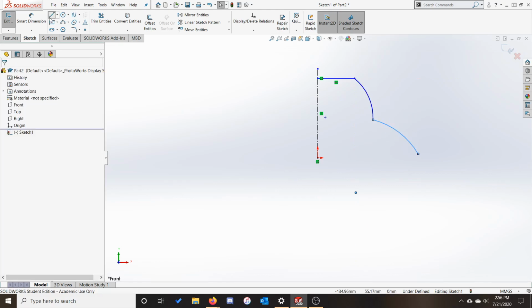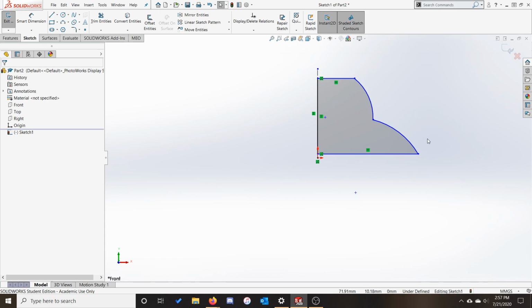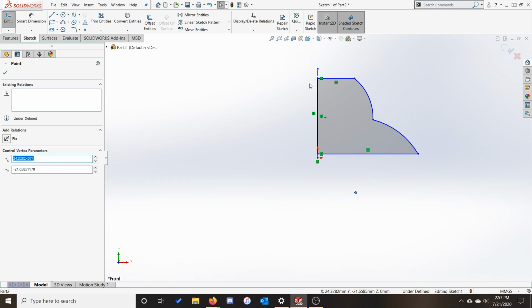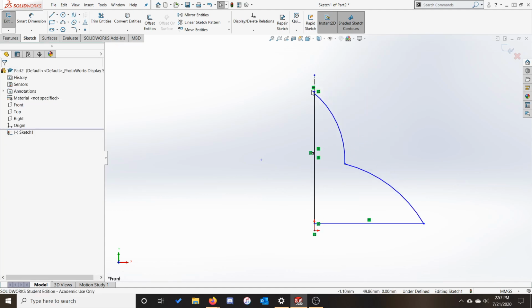Closing the profile can be something that is easily forgotten when dealing with revolve sketches, as oftentimes the edge that's collinear with your axis of revolution can be easy to miss. While we're here, I want the shade portion of this to be spherical. In order to get a sphere or a hemisphere shape, the center point of the arc needs to live on the axis of revolution. If it is anywhere else, the resulting shape is not going to be spherical.